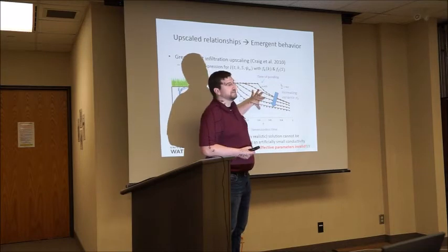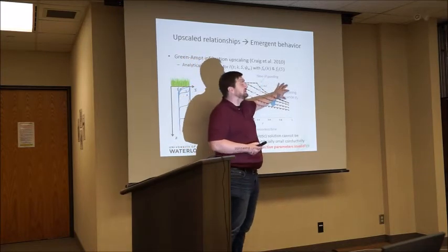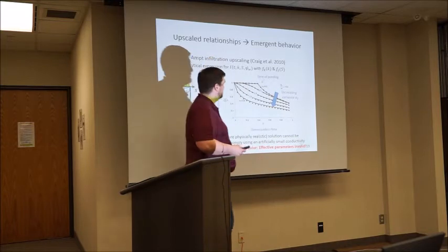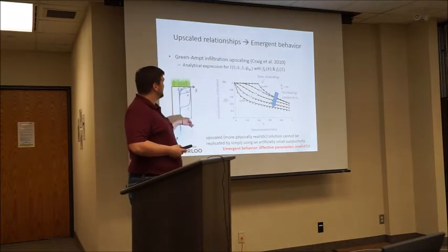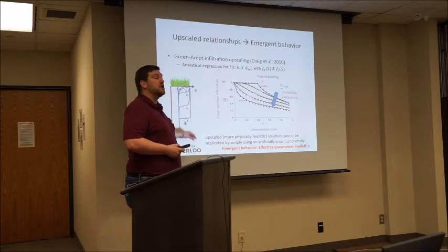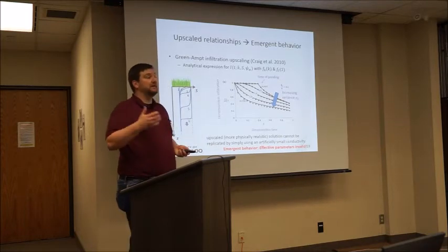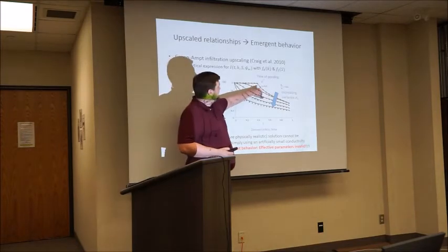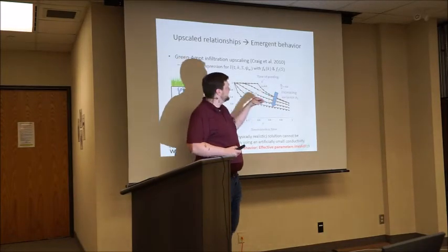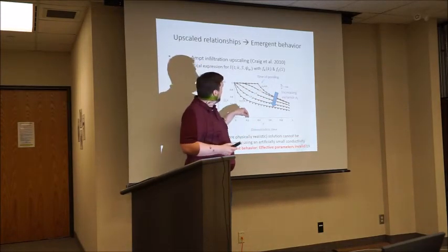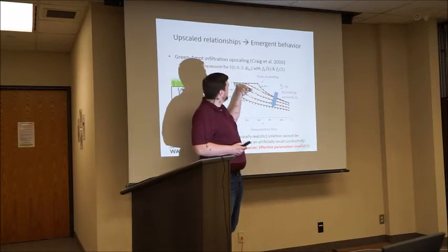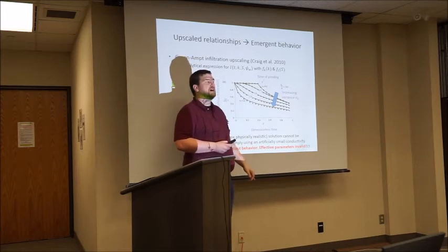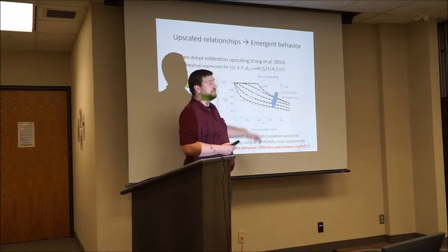Everything beneath this curve effectively ends up as infiltrating. Everything above this curve effectively ends up running off. So that's the classic Green-Ampt problem. And if we can solve this analytically, applying a PDF of saturated hydraulic conductivities, as you increase variance, you're basically averaging a whole bunch of these curves over all the parcels. And the average of a whole bunch of these curves with a sharp time of ponding is something that has no sharp time of ponding and a functionally very different behavior.